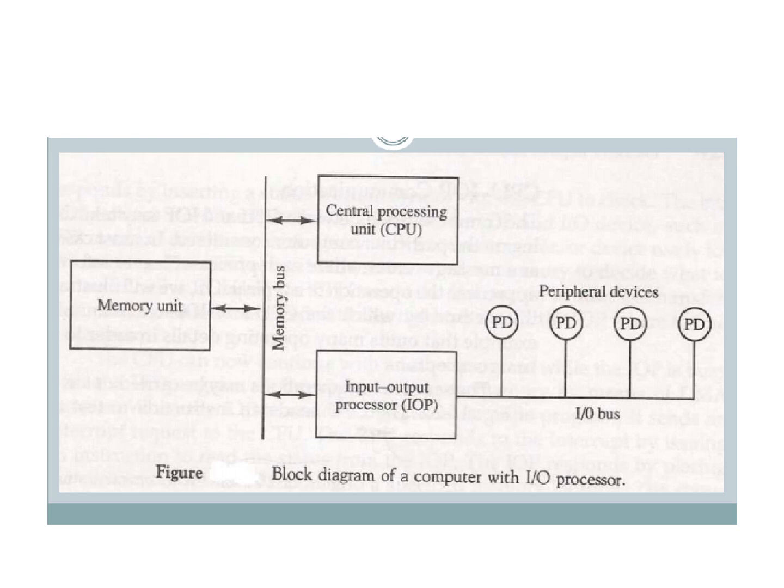Data formats of peripherals differ from CPU and memory. Data are transferred from input-output processor to memory by stealing one memory cycle. The instructions read from memory by input-output processor are called commands to distinguish them from instructions that are read by CPU.